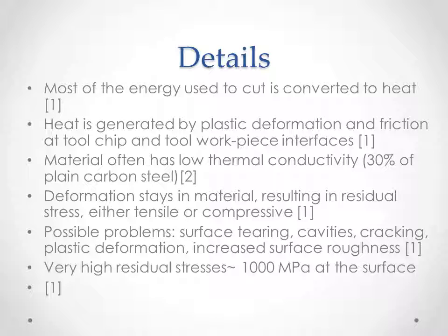So the deformation, if it heats up and the subsurface or the surrounding area does not heat up, a lot of deformation will stay in the material, resulting in residual stress. It could either be tensile or compressive. Possible problems, obviously the residual stress staying in the material, that could be a problem too, are surface tearing, cavities, cracking, plastic deformation, or even increased surface roughness.